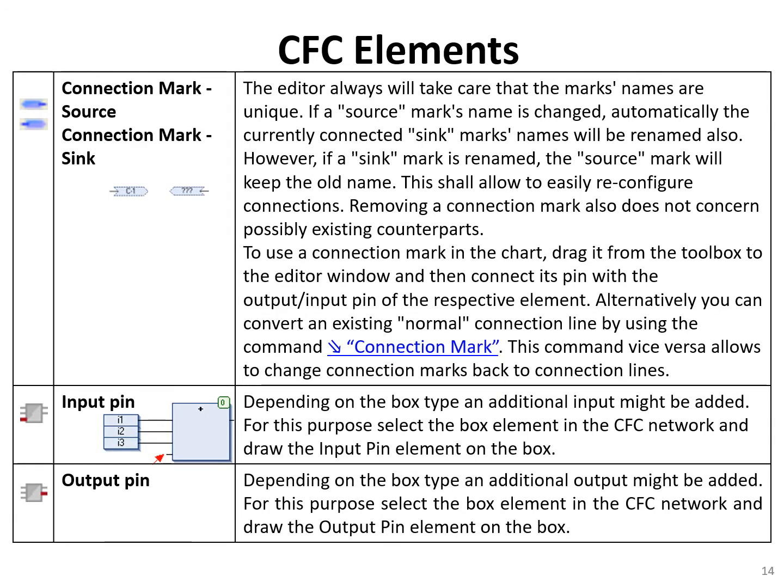The editor always will take care that the marks names are unique. If a source mark's name is changed, automatically the currently connecting sync mark name will be renamed also. So if you change the source name, don't worry about the sync names. The sync names will change automatically. However, if a sync mark is renamed, the source mark will keep the old name. Okay, so you should be careful about this one.